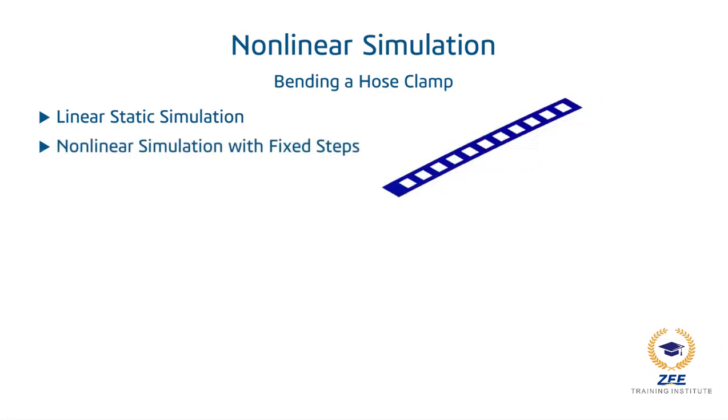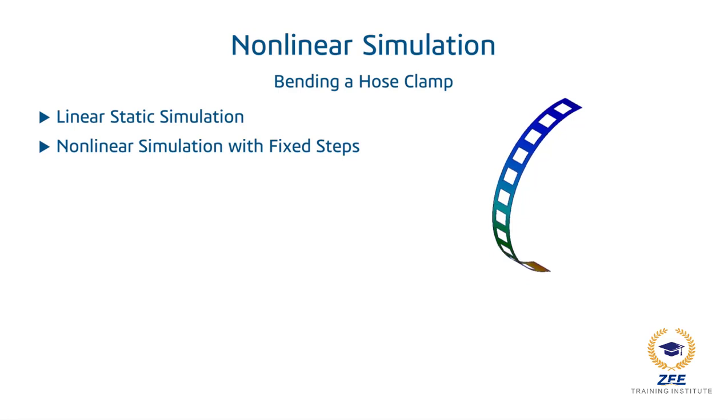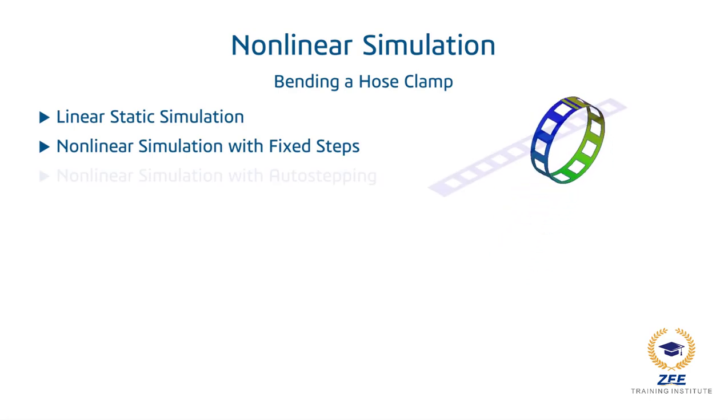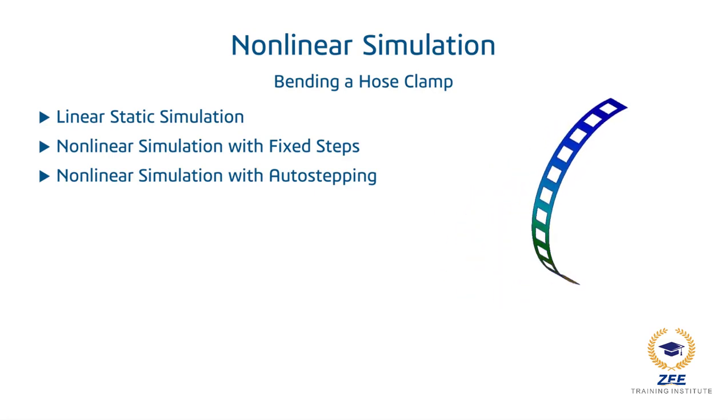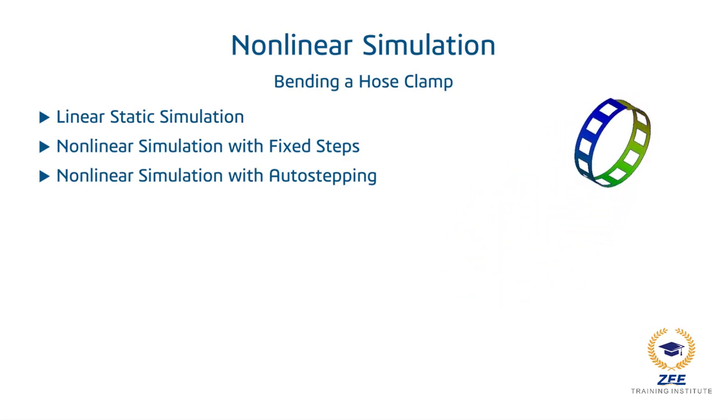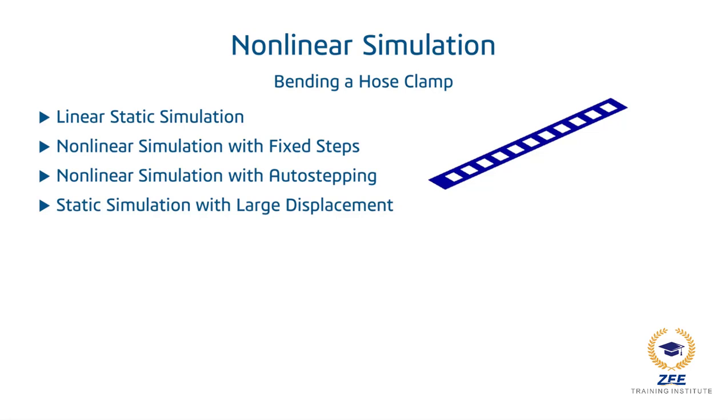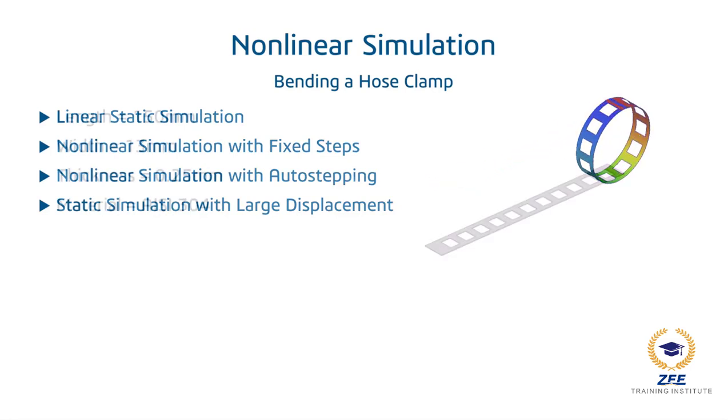the simulated event. We will define a non-linear analysis and solve it with fixed time increments. We will define a second nonlinear analysis, which we will compare with the first, that we will solve with automatically sized time increments. Finally, we will explore solving the problem using the large displacement option available in static studies.